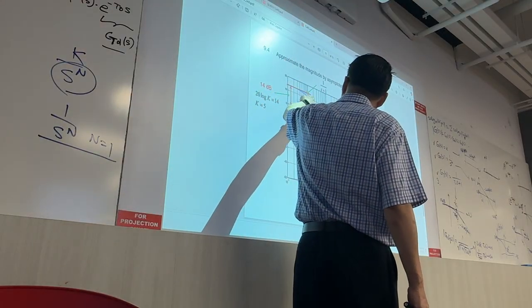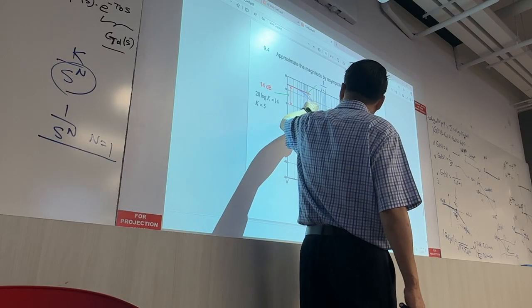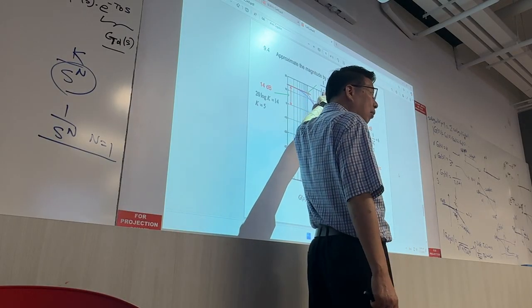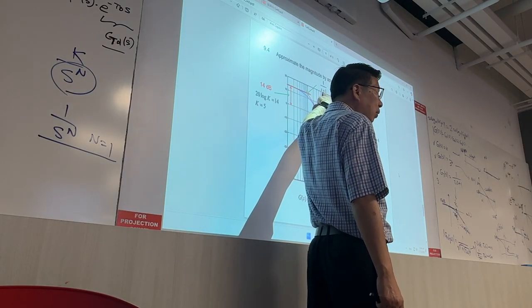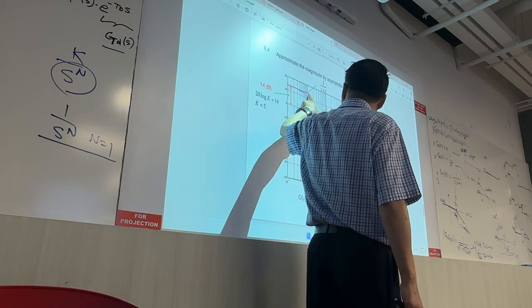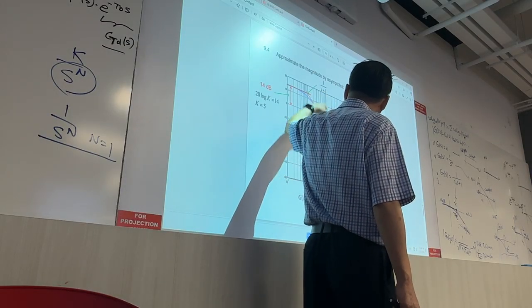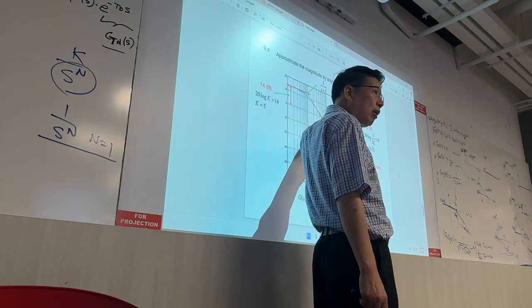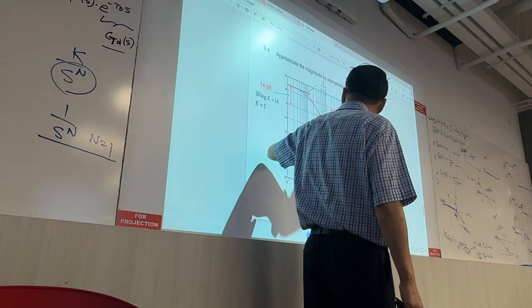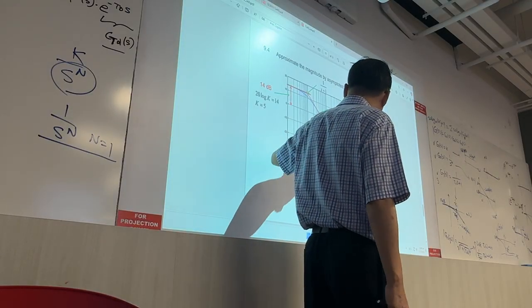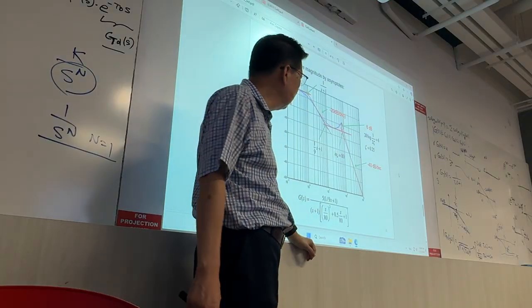Alright, and then from 0 to minus 40, minus 20, so we expect one basic factor in the denominator. And here there is a change of a net plus 20 dB per decade. We expect this to be from the numerator.